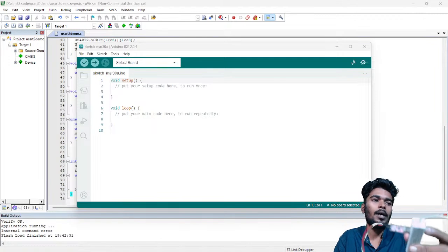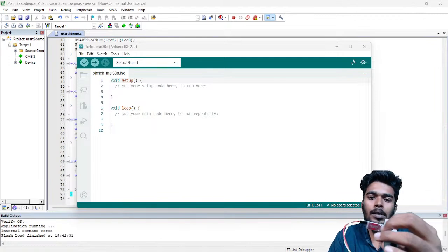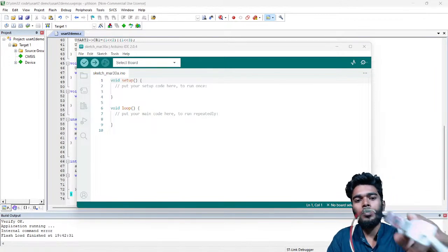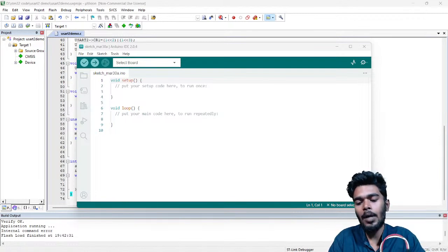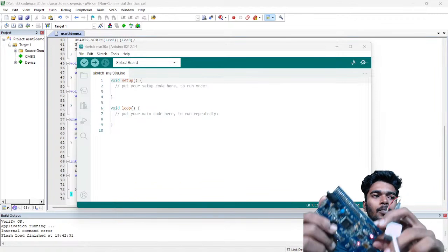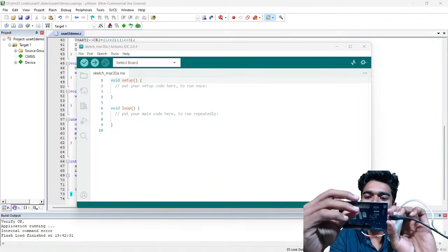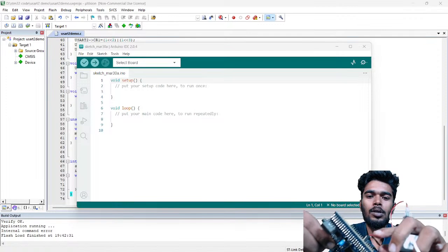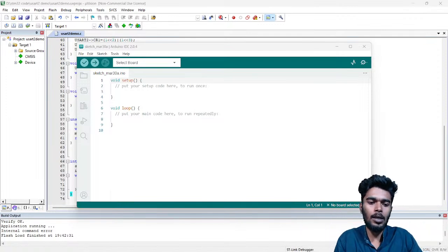So you can see we have a serial to TTL bus. We have connected this RX and TX pin. You can see the RX and TX pin with this board in the PA2 and PA3. So this is going to get the receiver, and we are going to see it in the UART in Arduino IDE.